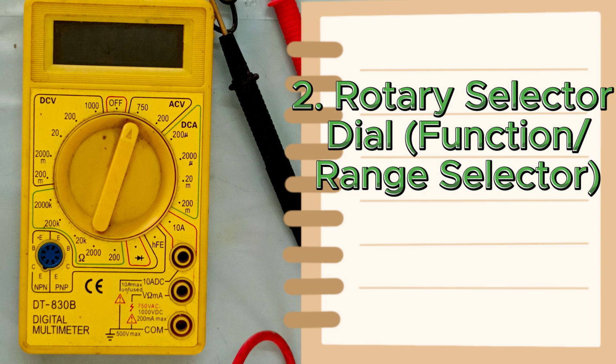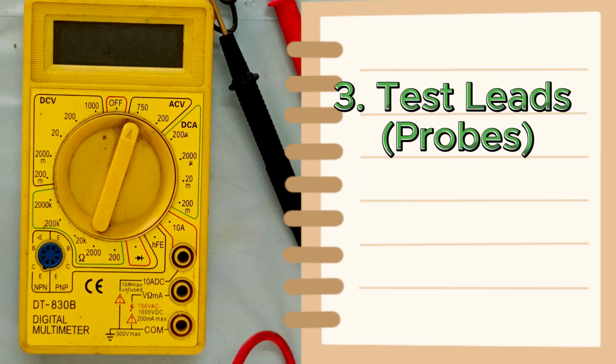Capacitance, nF, µF, mF, measures capacitance. Frequency, Hertz, measures signal frequency. Temperature, degrees C or degrees F, requires a thermocouple for temperature measurements. Impact: ensures proper mode is selected for accurate and safe measurements.